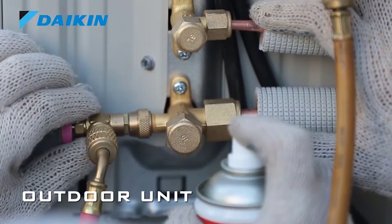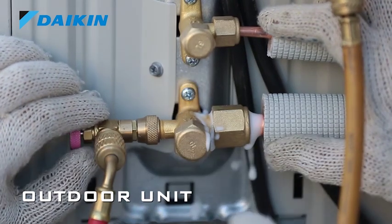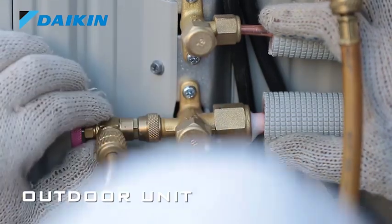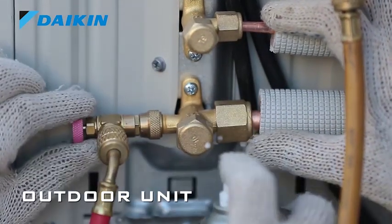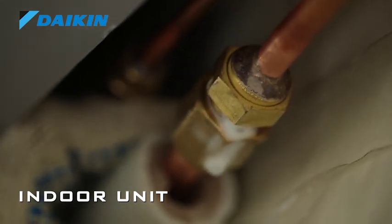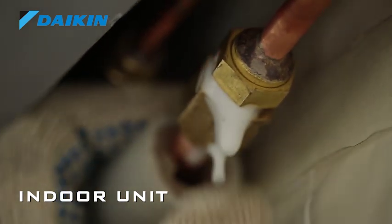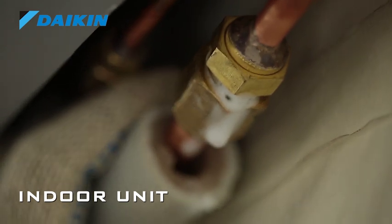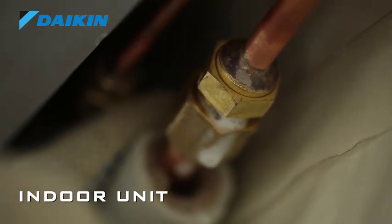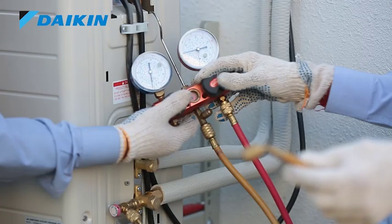Then apply soap solution from a soap solution can on all the flare joints to check any leakage. Carefully check for any bubble formation. If the soap solution bubbles, it would indicate a leak, which should be rectified before commissioning the AC. After the pressure testing is complete, release the nitrogen gas from the system.